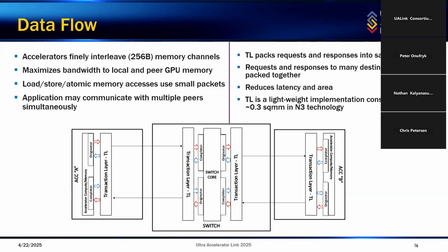Another issue is the concurrent communication amongst the set of GPUs within a group. A load store network supporting end-to-end frames with an Ethernet-like packet network, at a minimum, adds latency. To efficiently pack these small packets also requires supporting variable frames, as well as accumulating requests and responses per destination. These add significant area to the accelerators.